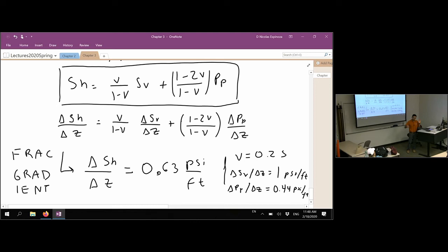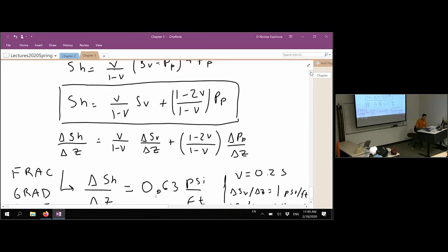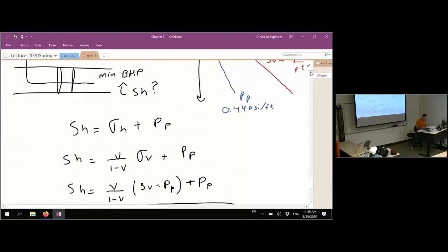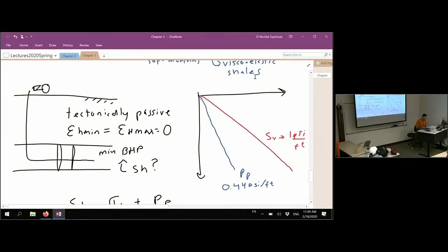That will be the pore pressure gradient. If we want to push a fluid, you want to be above the in situ pore pressure, right? Then we said we have the lithostatic gradient, and that will be the pressure needed if you wanted to lift the ground up in vertical direction.